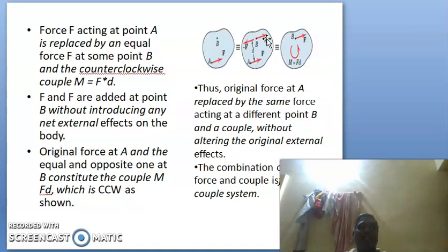And again, with that resultant moment we already obtained, we also add all the moments produced by the forces, and that also should be added vectorially with the moment. So we get one resultant moment and one resultant force, and that single resultant force and resultant moment can be represented as an equivalent single resultant force at a particular point where this moment can also be cancelled.